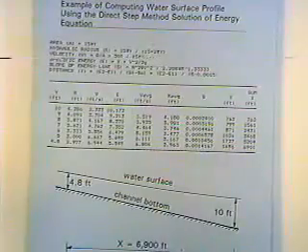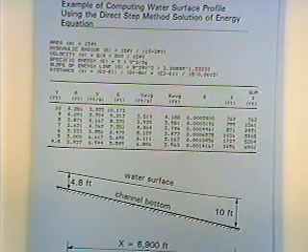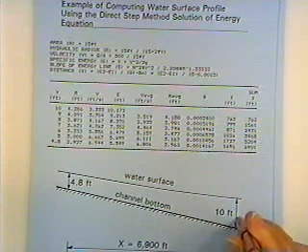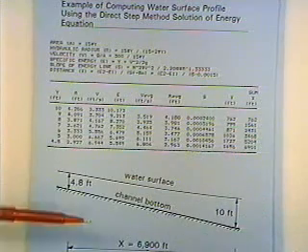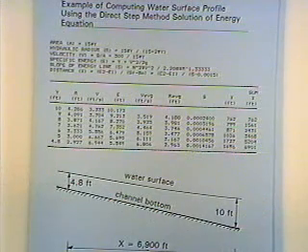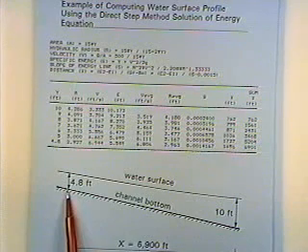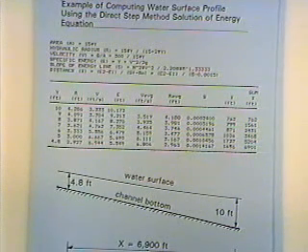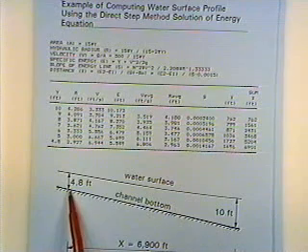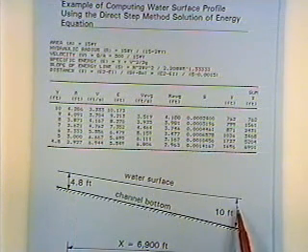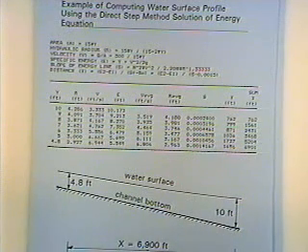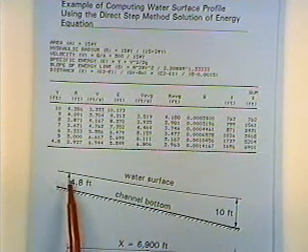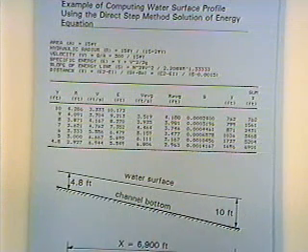On the bottom here, we've drawn the schematic. Coming horizontally out of the paper is the river, 10 feet deep. Then we've got the concrete channel emptying into the river. Someplace up here, the frictional forces and the gravity forces are in balance, and we've got a uniform flow depth of 4.8 feet. But this 10 feet is throwing it out of balance. We've got a backwater effect, a non-uniform flow. And we know there's no hydraulic jump, so I can draw that in as a smooth, gradually varied flow.